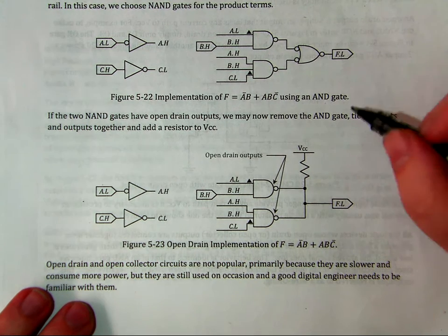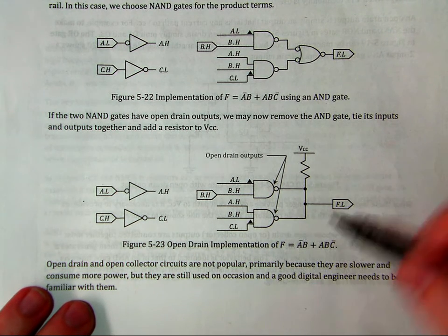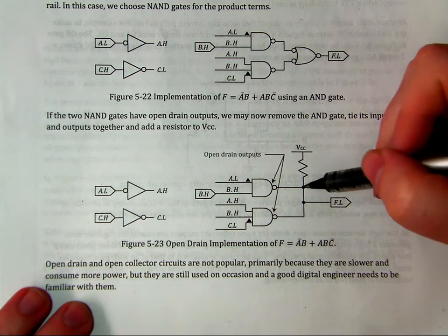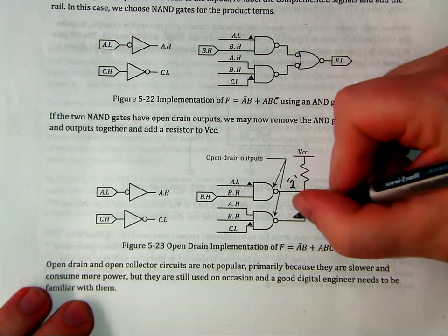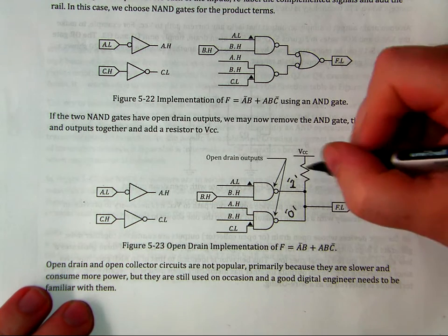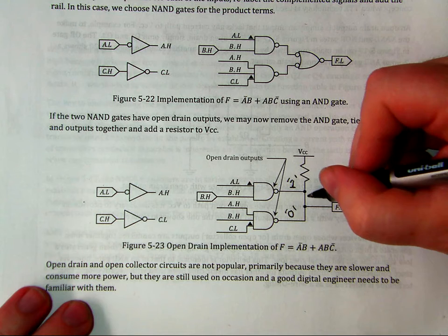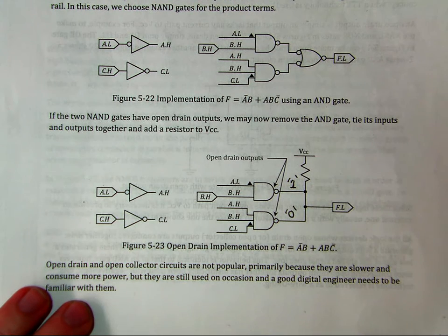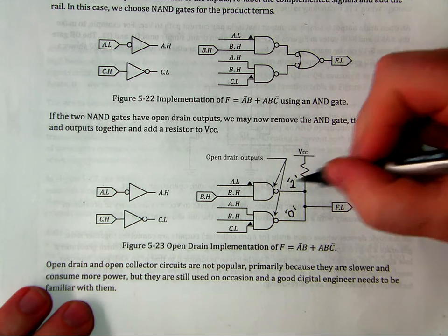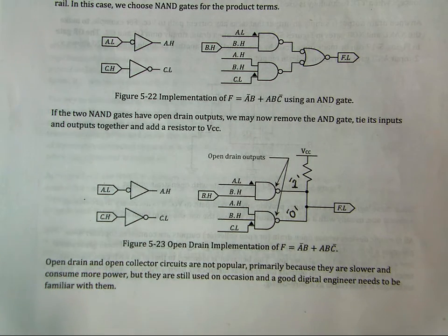So that's what open drain is used for, is for wire ORing, right? So if I want to output 2 connections, you could have a situation where this is 1 and this is 0, and if you weren't having an open drain, they'd fight, and this one would dump out a ton of current, and this would absorb as much as it could, and you'd potentially fry these devices. That's problematic. Having the open drain means I can do a wire ORing, which is kind of nice, but why not just design an OR gate, right?